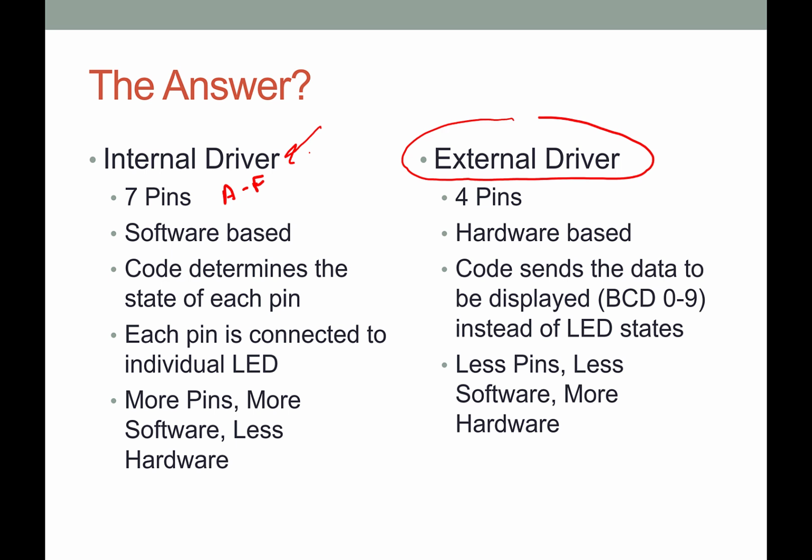And so this basically has a different kind of internal face. It's hardware based. And what do they mean about the one we're going to use for this? Well, I guess I should say, we have two. We're going to have the LCD on the board itself, but we're also going to have a decoder that takes 4 pins that would go to 16 pins. 4 bits could decode into 16 binary numbers.